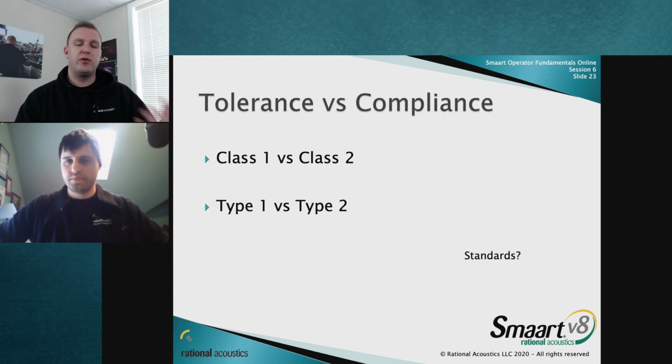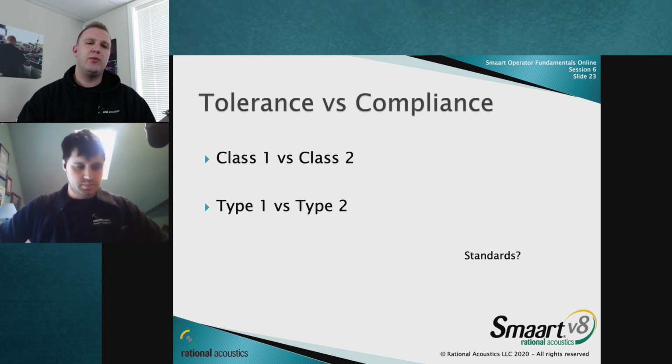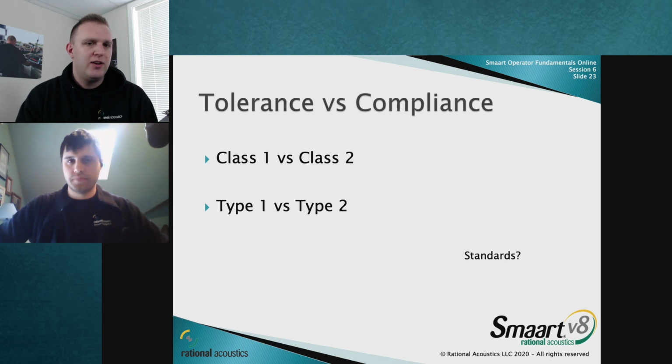There's a frequency component as well, and so when you look at a microphone spec sheet, you may see that this microphone meets frequency requirements for class 1 response, or meets the requirements for a type 1 SPL meter. Now, that's great. But it doesn't mean that your equipment is inherently compliant, right?